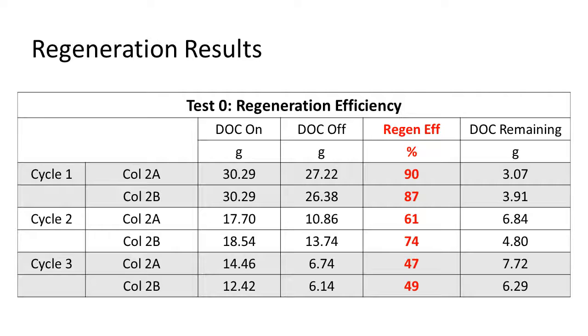And so, 90%: with sodium chloride at this level, we should probably be able to get a little higher. Some of that's probably the iron, some of that might be just the hydraulics of how we're doing the co-current regeneration. But we see a fairly substantial drop-off, which in the lab we probably wouldn't, because we wouldn't be having this iron issue. But we have iron fouling on the resin, and that's something we're having to wrestle with and figure out how we want to address.